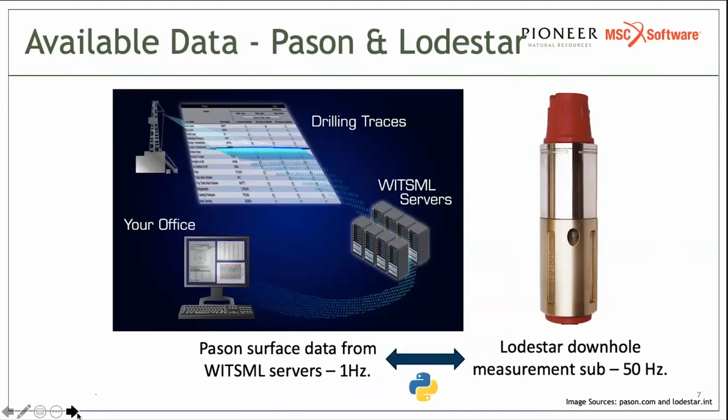Okay. Thanks, Jennifer. The next question is, how do you model the bit itself? Do you take into consideration the bit profile, the bit gauge, and the possible configuration, step gauge, back rake, etc.? Back rake is not something that we have in there, but the bit model does take into account, for example, how many blades you have on the bit, how many cutters, and where those are located.